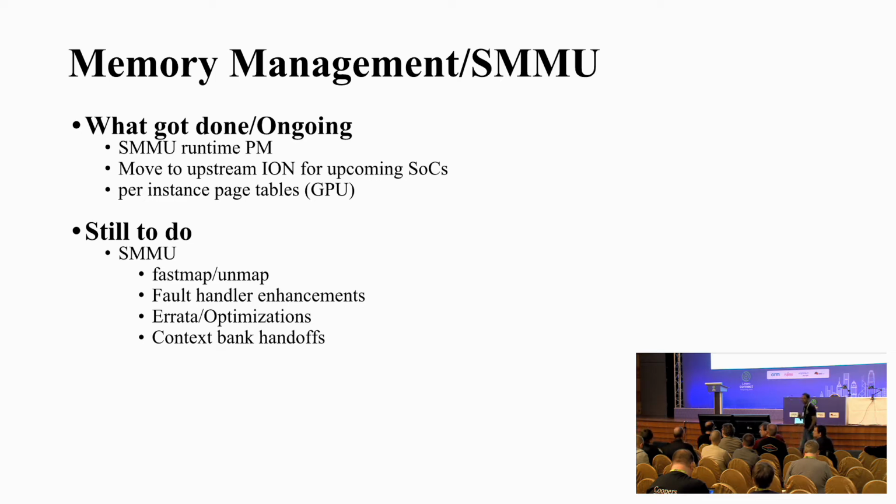I mean, there is more than just context bank handover, but how does the kernel find the scan-out frame buffer if, like right now, we describe it as a base address and a size, not like a scatter list of pages. Plus, why is finding contiguous memory a problem for the bootloader? Yeah, I'm not sure why we are doing it this way, but that's what we saw was done on the Android bootloaders. Vivek, do you know why?